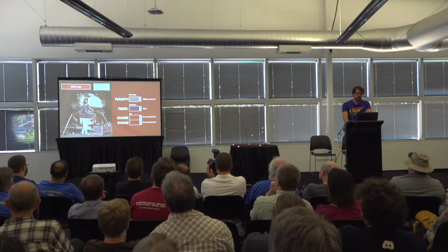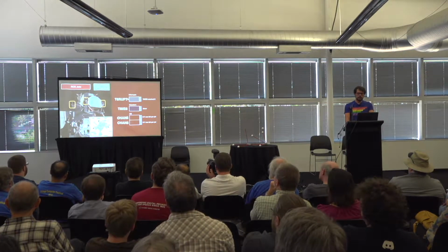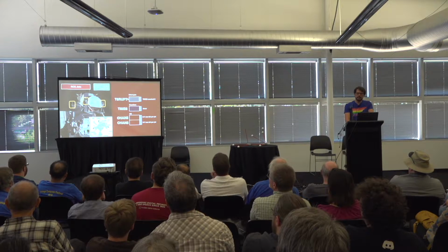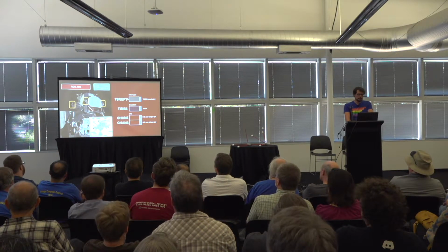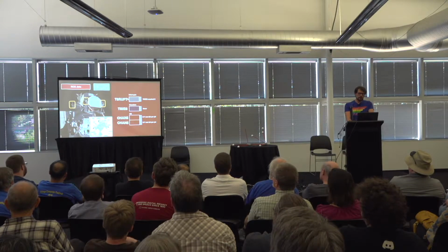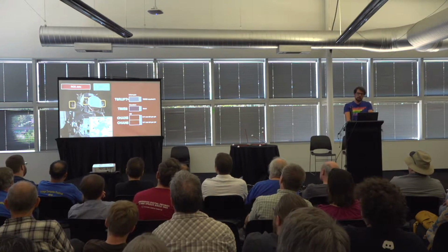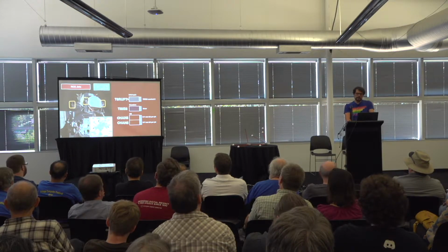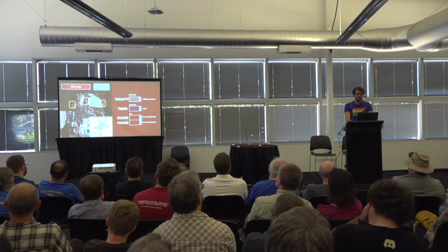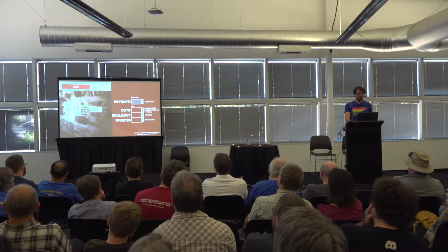The command module, the service module, and the Lunar module all contain reaction control system, RCS, jets, that emit small bursts for holding or changing the attitude. On the Lunar module, there's 1 bit for each of the 16 jets. Setting a bit to 1 will make the jet fire. The system software uses a dedicated timer, TIME6, and its interrupt, T6RUPT, for timing the pulses.